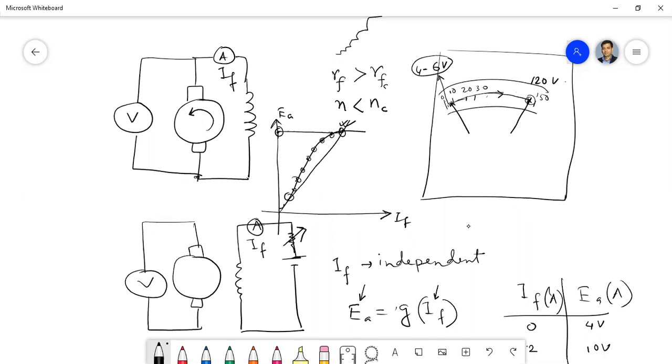this type of normal analog voltmeter or maybe digital voltmeter, you can measure only the stable voltage. If there is some fluctuation, if there is some transient, you cannot track that. You cannot measure that. If you want to measure any transient kind of thing, then you have to go for a different kind of measuring instrument, maybe some storage instrument, some storage oscilloscope also. So this type of normal voltmeter, ammeter can measure only the stable point, only the stable voltage.